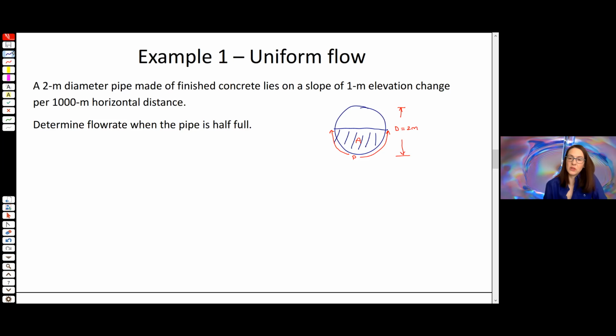Okay, so now we're going to use the 10.17 version of the equation, the Manning equation. And right, Q is equal to, first we'll just write the fundamental definition of the volumetric flow rate, right? The cross-sectional area times the mean velocity. But also by equation 10.17, it's equal to kappa over N, cross-sectional area A, hydraulic radius to the 2/3, slope to the 1/2.